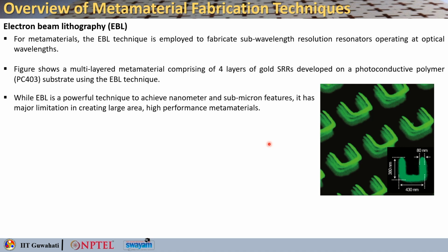Large area patterning with multiple stage moves results in poor resolution and stitching defects. Stitching errors also hamper the ability to repeat the patterns over a large area without any misalignment problem.